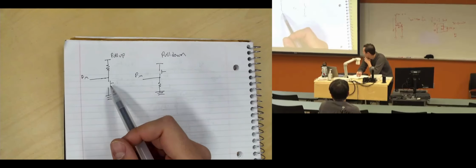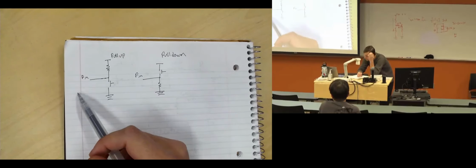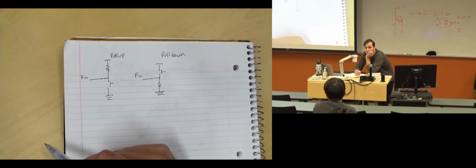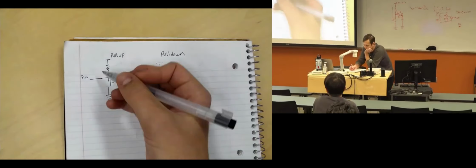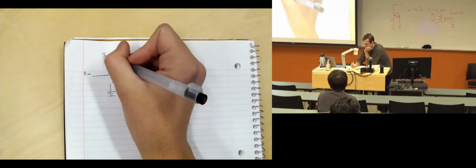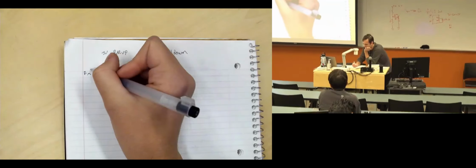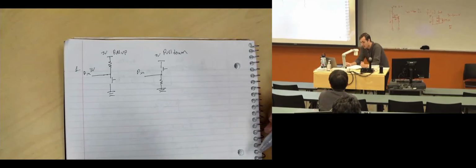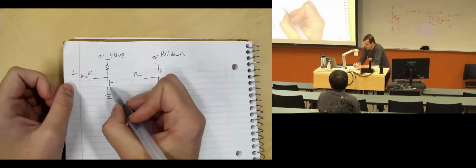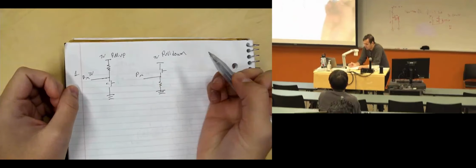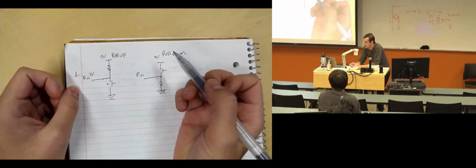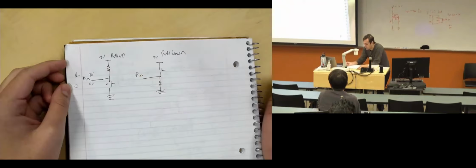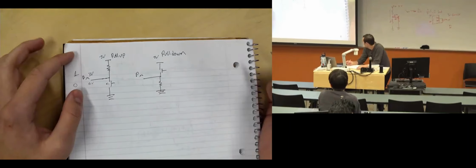When this switch is not pressed, what is the voltage on the pin? High, great. Whatever our voltage is, we'll just call it 3 volts. So you'll get 3 volts here, and you'll get a 1 in your processor, right? And when you press the button, this is pressed down, what value goes onto the pin? 0, right? So you get 0 volts here, and we'll read a 0 onto our pin. Great, so this is good for the first one.